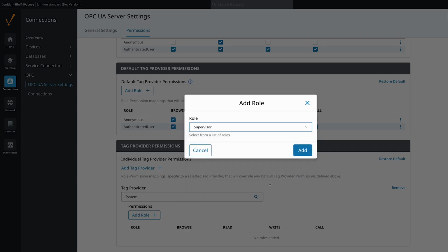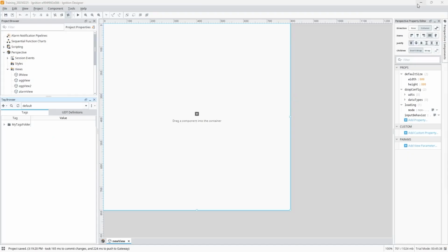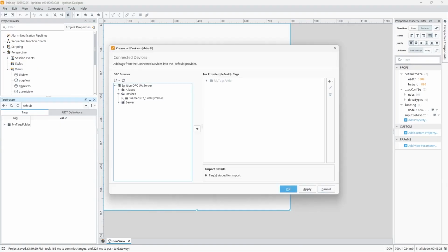Ignition 8.3 updates the Siemens S7 driver with improved support for browsing, symbolic access, and access to optimized databases. This driver provides direct access to your Siemens S7 PLC input-output channels using function blocks that do not require manual mapping or reconfiguring of every connected device for each change.